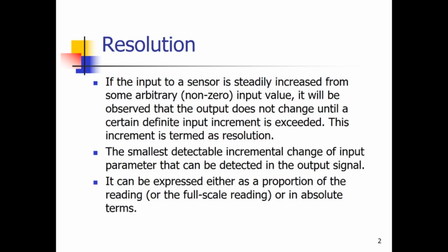Or in other terms, we can say it is the smallest detectable incremental change of input parameter that can be detected in the output signal. So, this term resolution is also expressed either as a proportion of the reading with the full scale or in absolute terms.